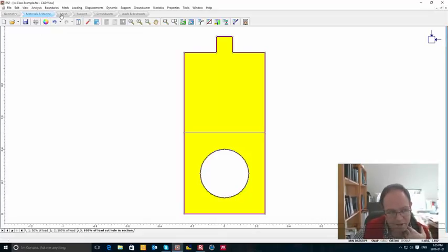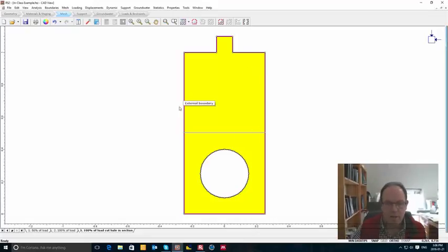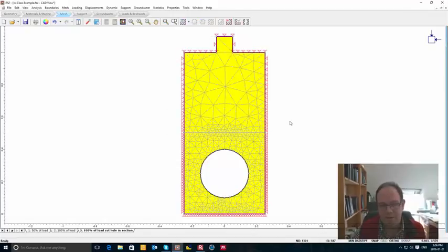So the next tab is the mesh, and that can be fairly involved. We're going to first discretize the domain by pushing this button. Okay. And you can see it put a bunch of nodes around it. And then when we push mesh, it will basically use those nodes to make some kind of graded mesh automatically. See, watch this. So there you go, made a mesh.